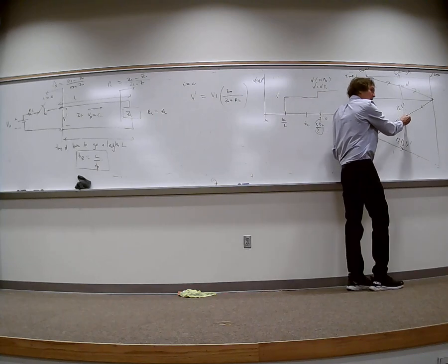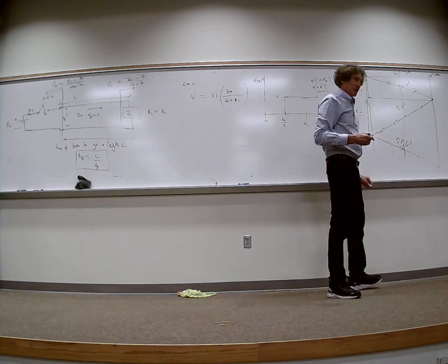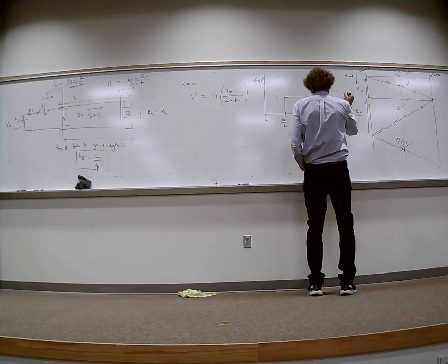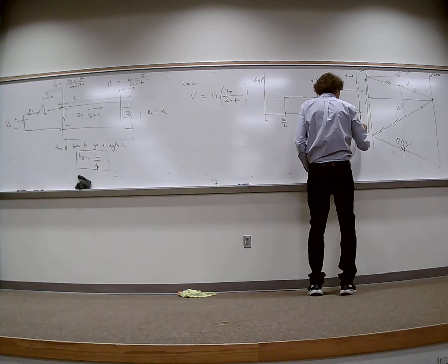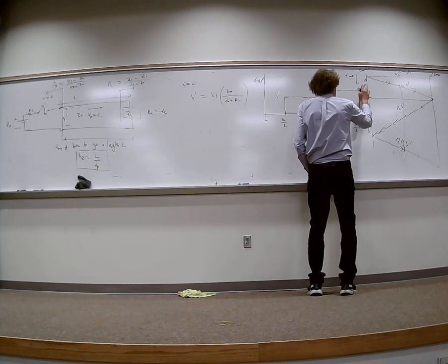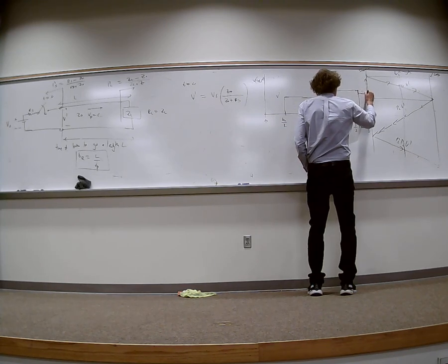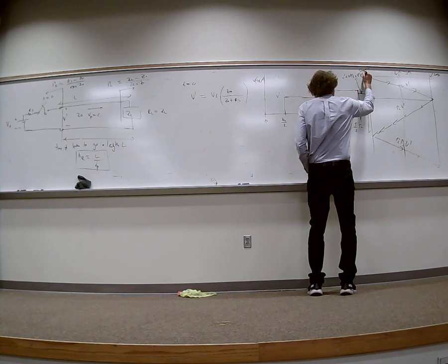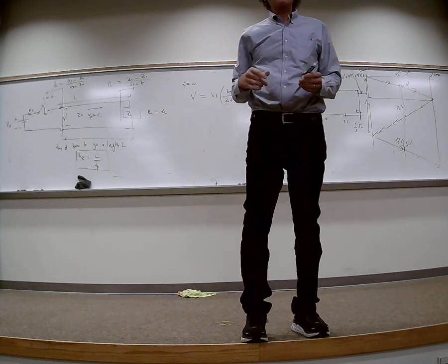Well, another full TL, right? And then what happens? Then I add this onto it. You all with me? Then I'm going to add that on. I keep going, so down here to 5 halves, down here somewhere, and this is where it gets messy. So this would be 5 halves TL. And now it's going to jump up. It's going to go either up or down, I don't know, I'm going to have it go down, but now it's going to be V prime plus V prime gamma L plus V prime gamma L gamma S. Do you all follow me? How many see this? And you just keep on letting it progress.